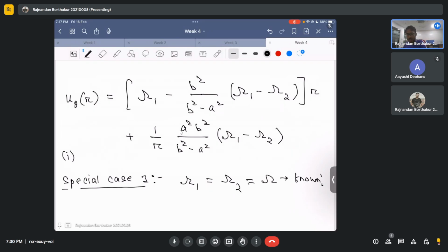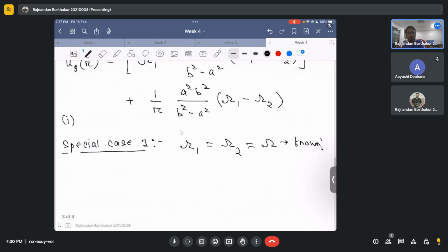Okay. And also, without losing any generality and for simplicity in understanding, let us consider that dp/dz is basically 0, which means that I have stopped the axial pressure gradient. This means the flow field will now just be a one-dimensional flow field bearing only the theta direction velocity, and uz will basically be equal to 0. This is just for simplicity, as we are dealing with special cases here.